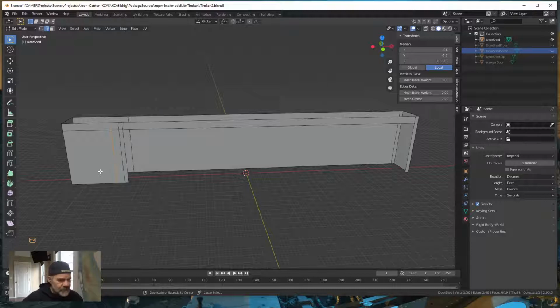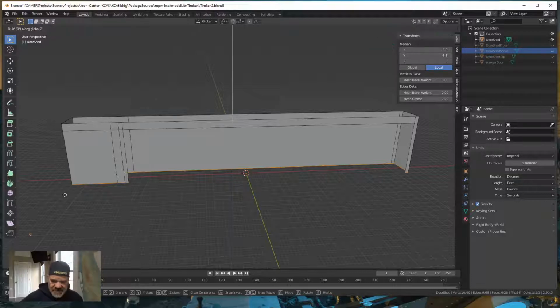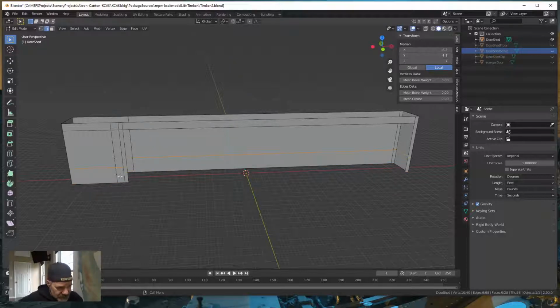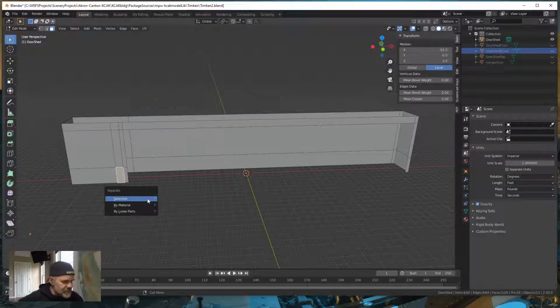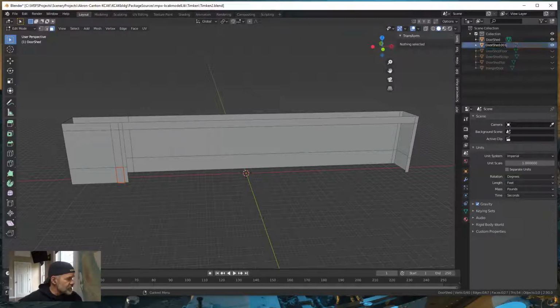So Control R, click, drag that down to the bottom, GZ, because we're moving it up now, 7 feet. And now we have our person door right there, our P door. So go to Polygon Select, select that little rectangle, hit P for new selection, and come over here and rename that. And I'm going to call that Door Shed P Door.